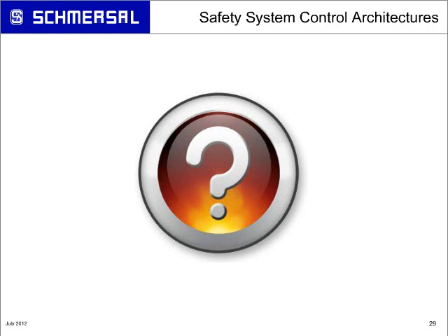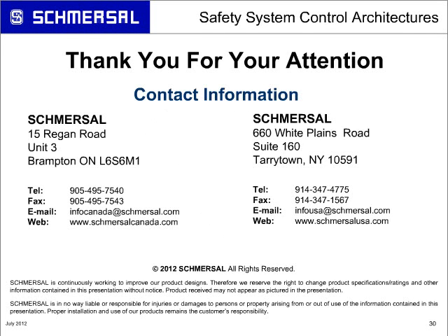Most of the time you end up only achieving up to a control category 3. The main reason is it depends on the type of device you're working with, such as an electromechanical key. If you still have the chance of mechanical failure, you're only going to be up to that control category 3 safety level.